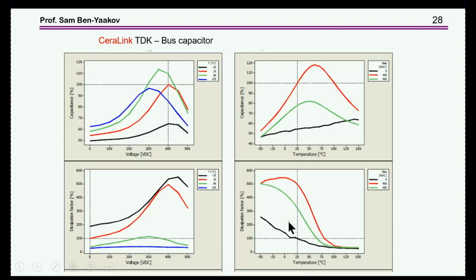temperature. That is, you cannot get the good characteristic if you operate them at 25 degrees or 50 or 70. You have to operate them at 150 degrees. This will be the self-heating plus the ambient. Okay? So here you see it. For example, dissipation factor. At 25, here it is. This is with DC.